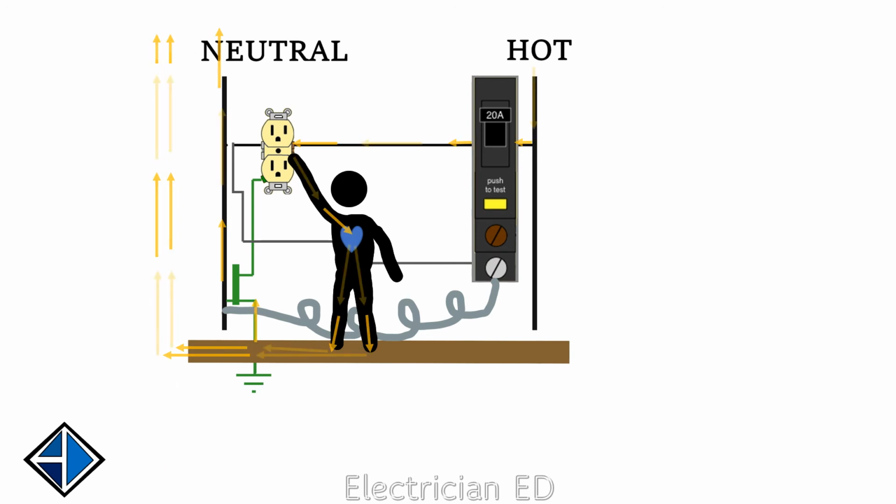It's actually based on a magnitude time curve. So how much current is going through will determine how long it takes to trip. And that helps to avoid nuisance tripping. But as soon as it detects it, it's going to trip the breaker. And then we've got the potential just waiting over here again.